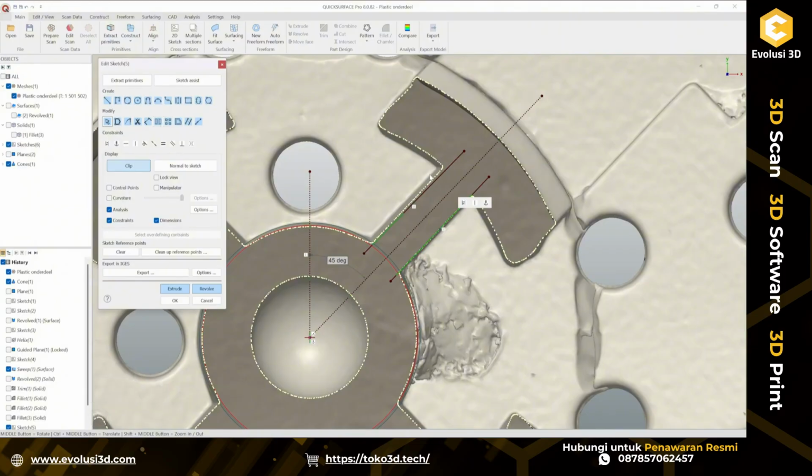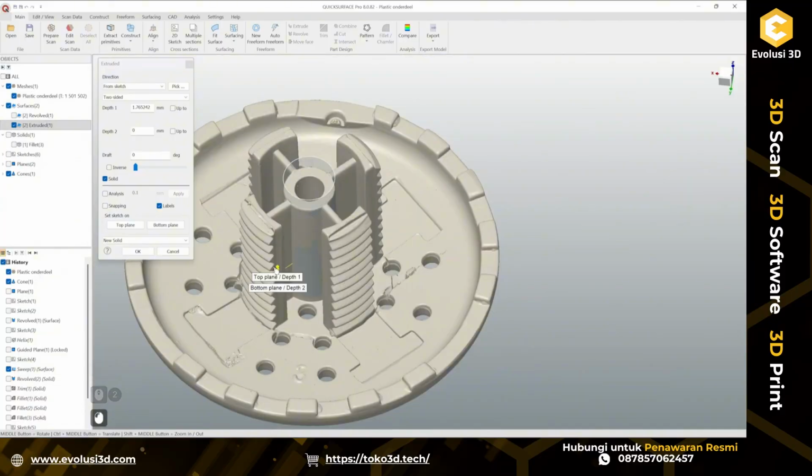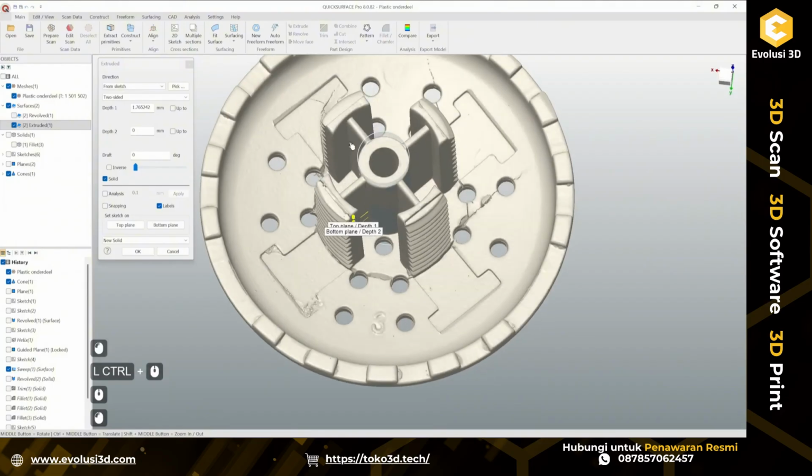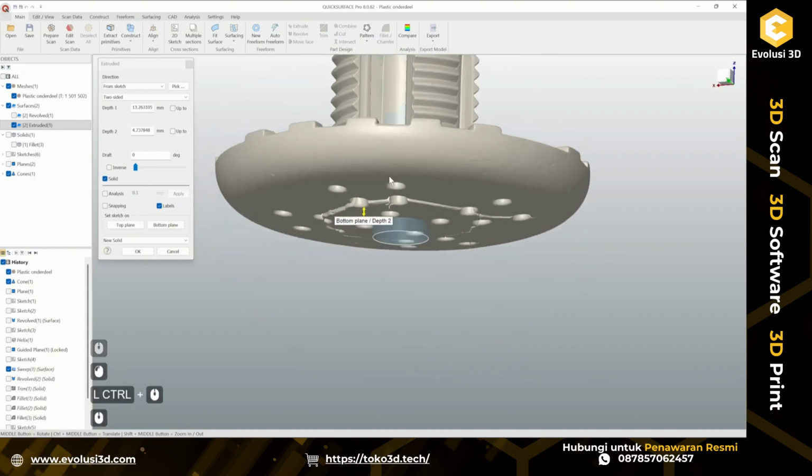But yes, again, this is first of all a plastic part, secondly it's broken, and again we have to find some logical way how to create this. So if we want to create this as a perfect CAD, probably this would be a correct approach, but at this moment we have to understand that we will see more deviation at the end. So this is something to consider. Okay, so once I have created these two profiles, I can extend extrusion height to intersect completely my solid. Okay, like this.